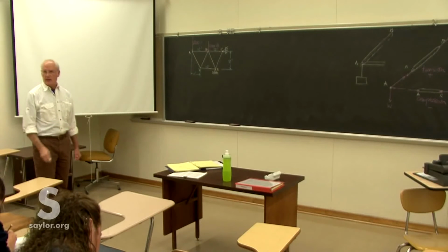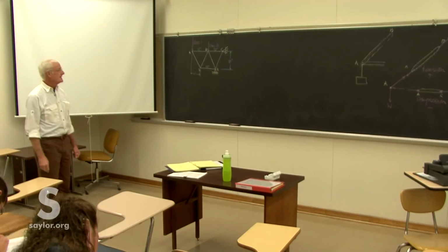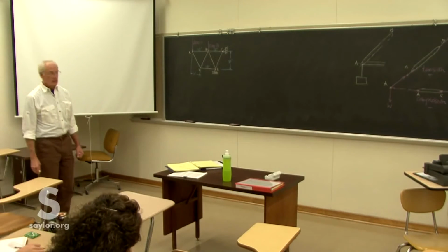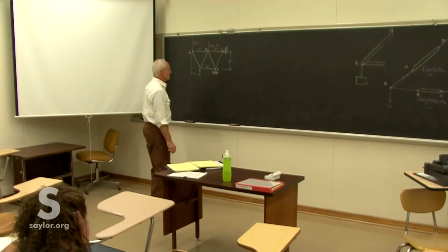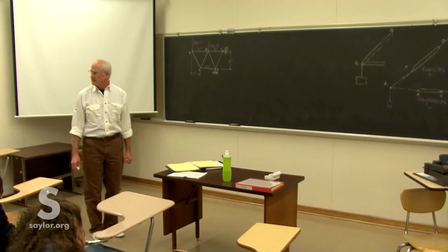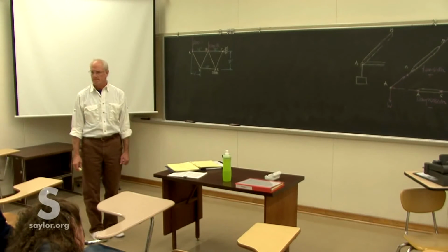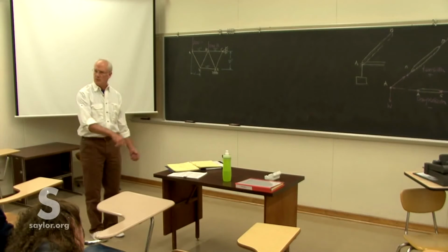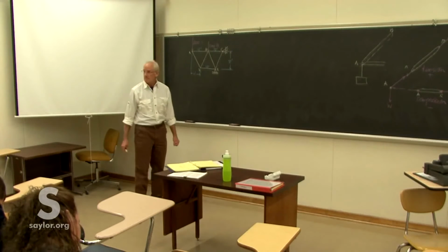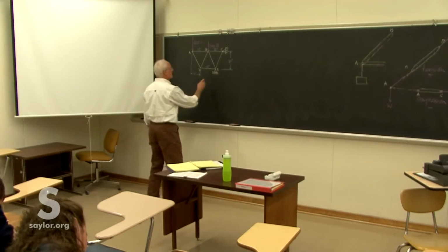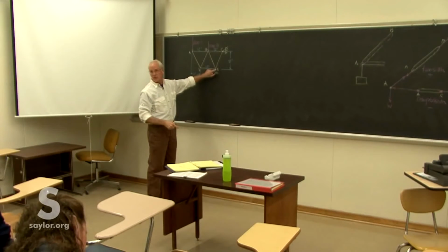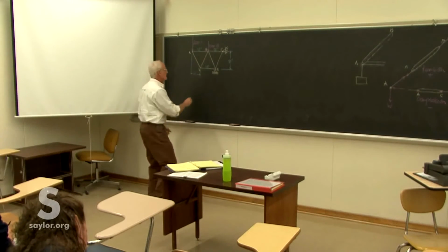And we want to analyze the forces in each of the members. It's possible that we can make some design decisions when we know that. First step. First step, look at where I listed the steps. What did I say? Free body diagram. Yeah, free body diagram of the whole structure, the entire structure, because we need to find out what these reaction forces are, because that's going to determine the forces in each of the members.